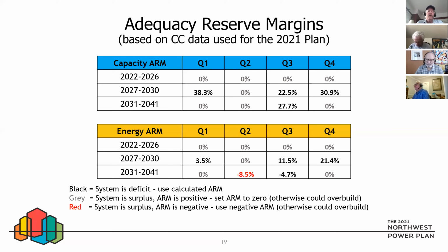So the 2,500 megawatts that John mentioned, the long-running discussion in our committee about this, with a lot of discussion with Bonneville about the transmission side. First of all, you have to consider the possibility that the DC intertie just isn't available. We've had 4 instances of that in the last month for brief outages. So on peak, that's an N-1 contingency. We really can't count some portion of the intertie capacity being available when we actually really need it. So the question has been, do you want to raise from 2,500 to say 3,400 megawatts or thereabouts? And that discussion is still going on.